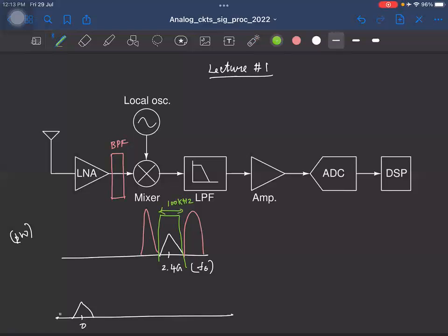Okay. And not just that, this filter should not have a fixed center frequency. As you know, every time you make a call, the center frequency will keep changing, right? So this bandpass filter must also be programmable, right? So as we'll see in the course, using LPTV systems, we can actually design very good programmable sharp bandpass filters with very small bandwidth. Okay. So I guess that should convince you that LPTV systems are okay.